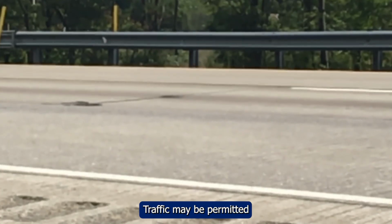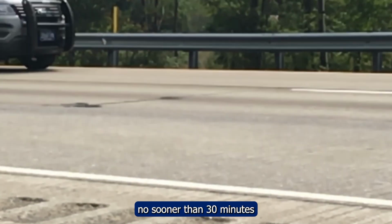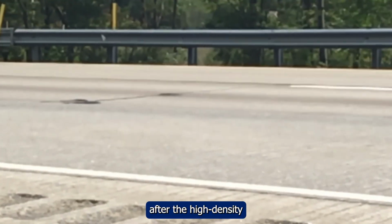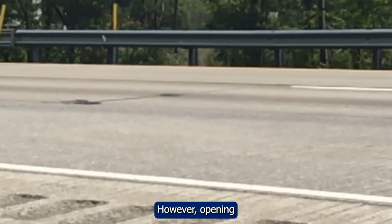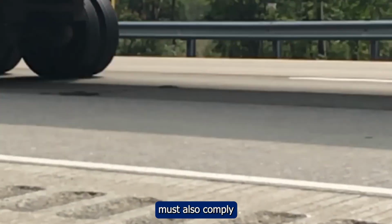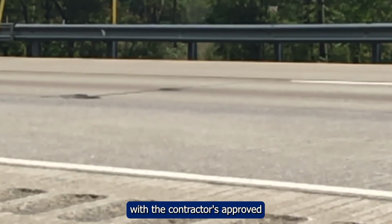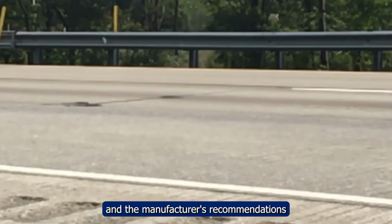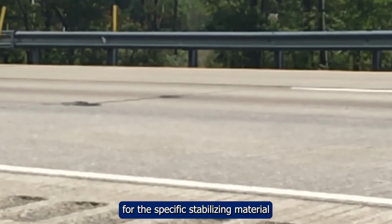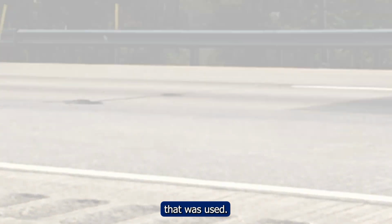Traffic may be permitted on the stabilized pavement no sooner than 30 minutes after the high-density polyurethane grout injection is complete. However, opening to traffic times must also comply with the contractor's approved field quality control plan and the manufacturer's recommendations for the specific stabilizing material that was used.